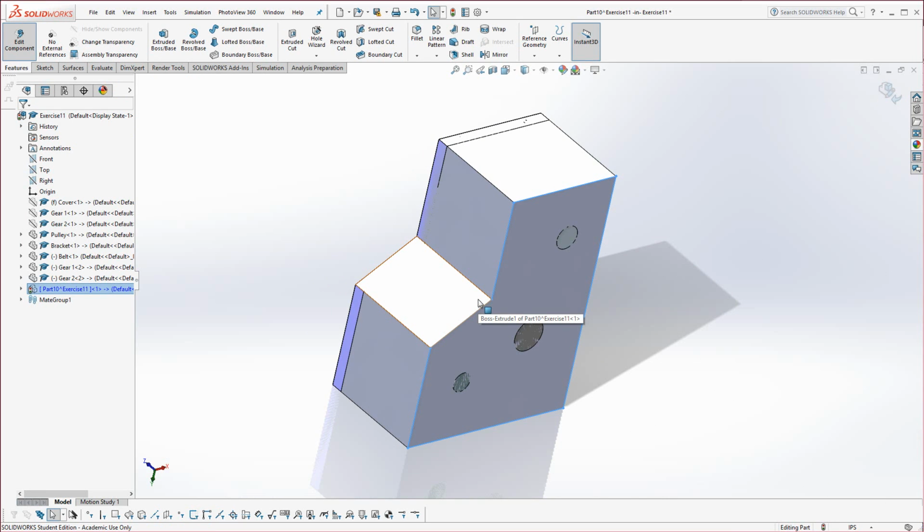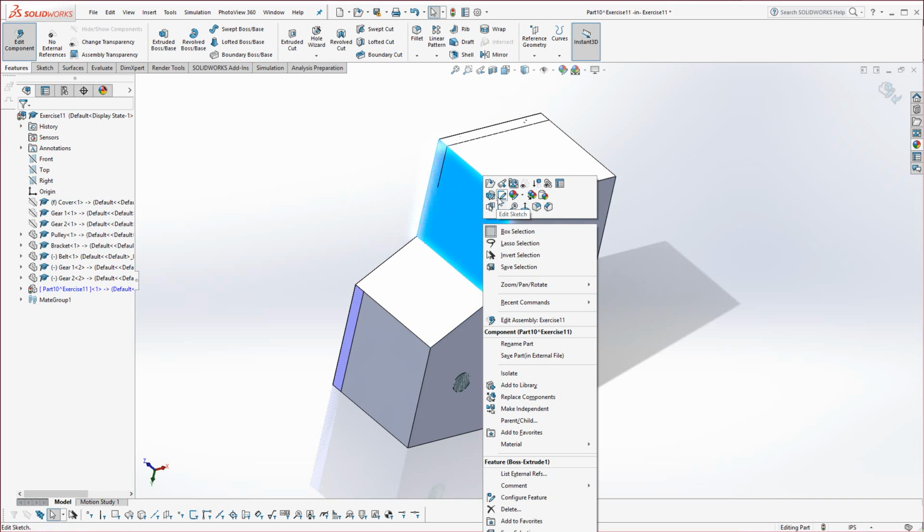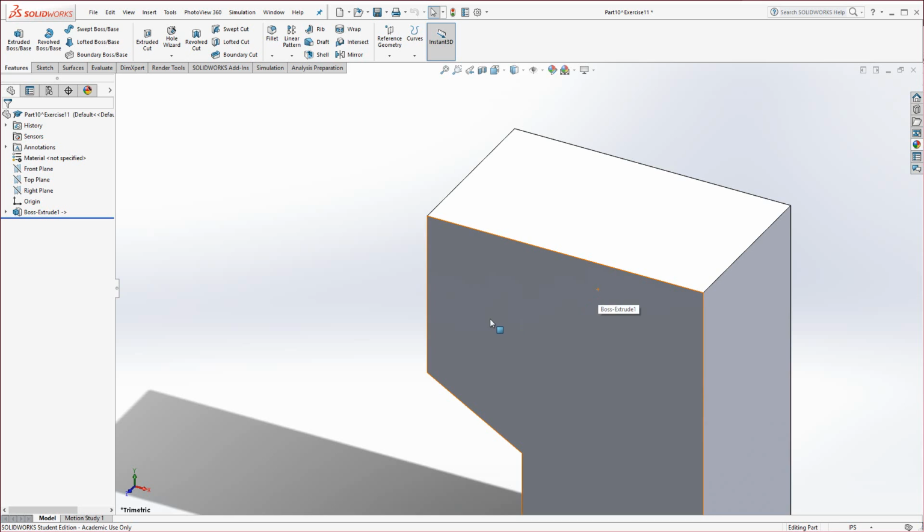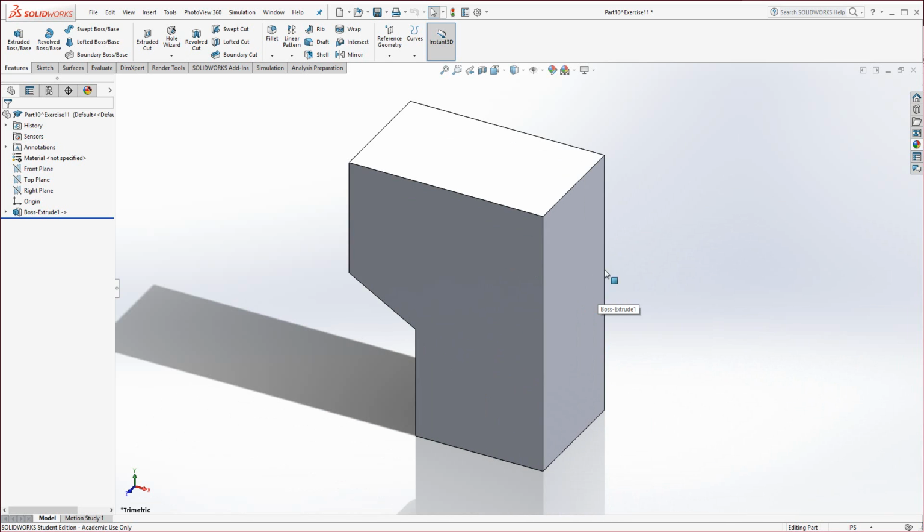What we're going to do, we're starting off with a solid, we're going to shell it and then convert it to a sheet metal part. That's one method of doing these things inside SolidWorks. Okay, now that we actually have that there, I'm going to right click on it. We click on the part and we want to open it up. This is going to isolate that part by itself and keep it in this view that we currently have.